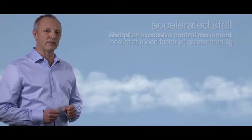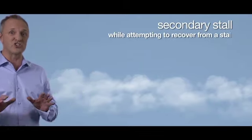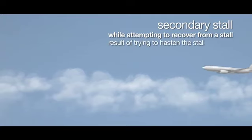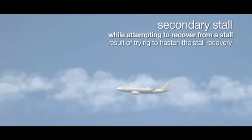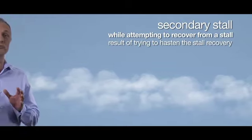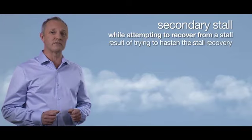Secondary stall. A secondary stall may be triggered while attempting to recover from a stall. This usually happens as a result of trying to hasten the stall recovery, either by not decreasing the angle of attack enough at stall recognition, stall warning, or by not allowing sufficient time for the aircraft to begin flying again before attempting to regain altitude loss.